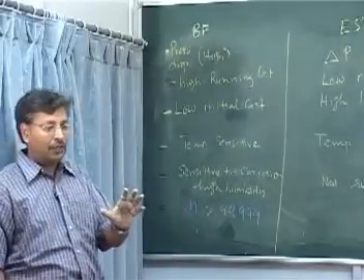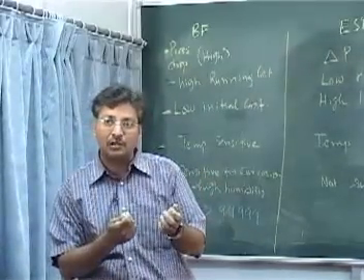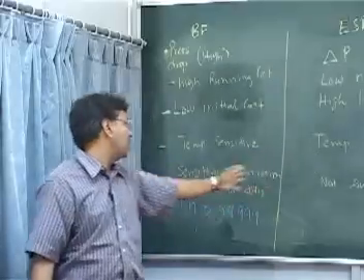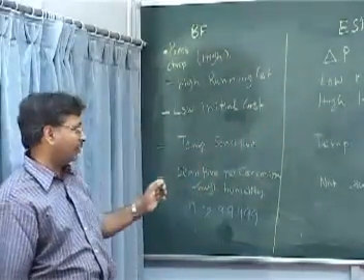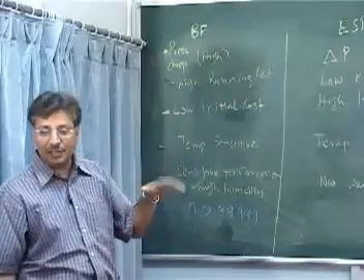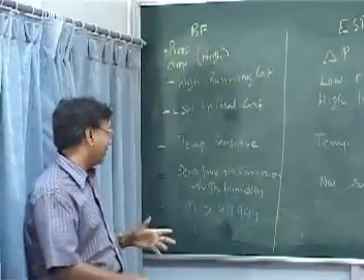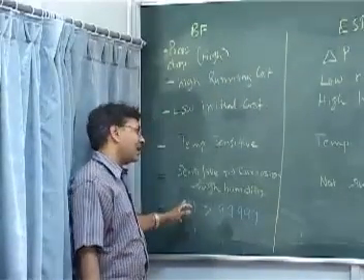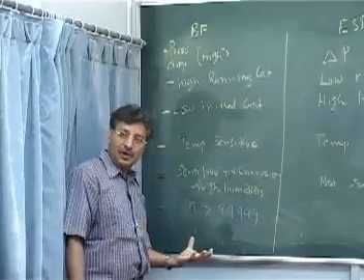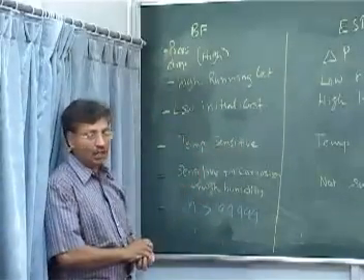Suppose you are working in a gold processing unit and the gold is in the form of particles. You will not go for the ESP, you will put the bag filter. These costs are insignificant for me, because if a little gold escapes, I lose. I am just giving you a very coarse example. Take the cement industry: cement is a product, so they will have this, because the efficiency of the bag filter is high.